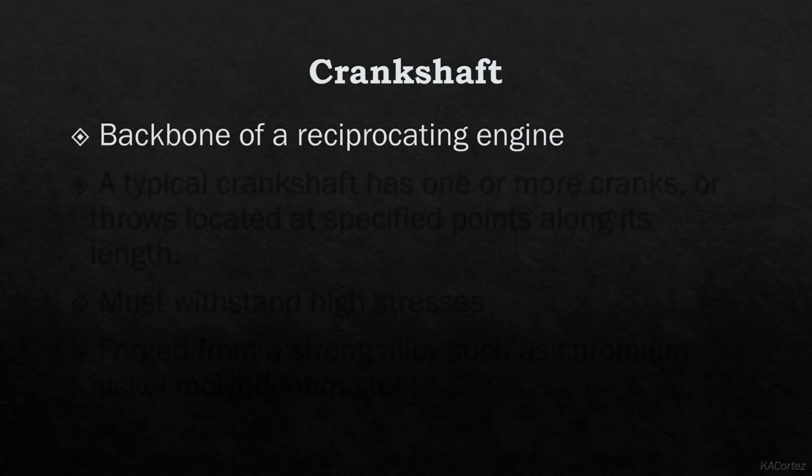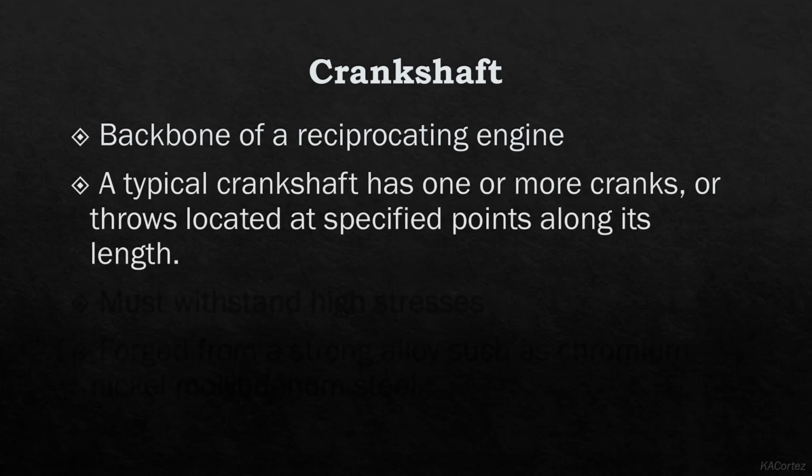The crankshaft is said to be the backbone of a reciprocating engine. Its main purpose is to transform the reciprocating motion of the pistons and the connecting rods into rotary motion to turn a propeller. A typical crankshaft has one or more cranks or throws located at specified points along its length.